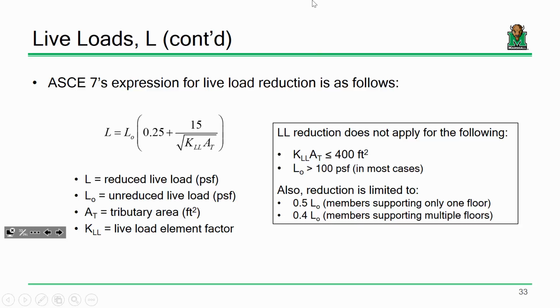No, that's a good question. Can you apply live load reduction to bridge design? The answer is no, because the actual load model that we use for bridge design is fundamentally different. We're not applying a blanket 40 PSF or 60 PSF. That's really not the way it works.